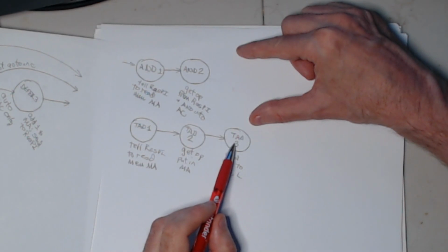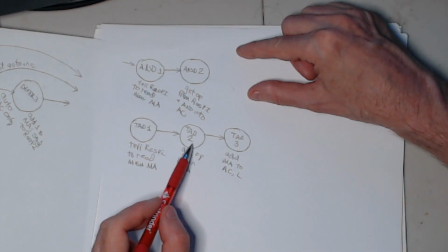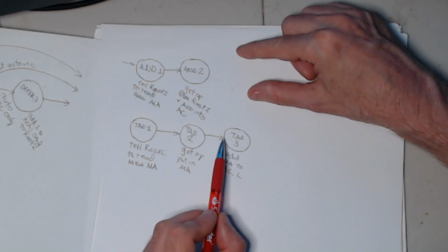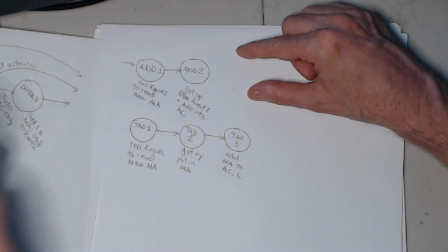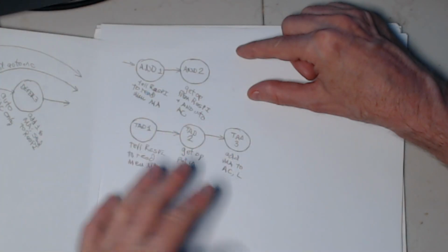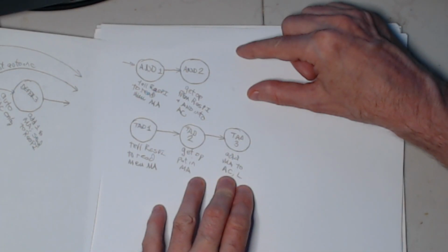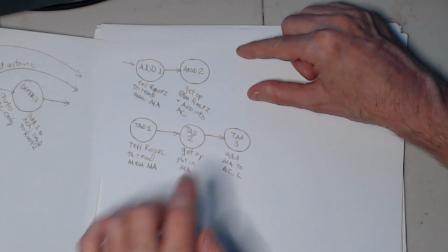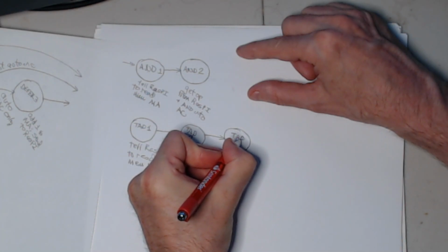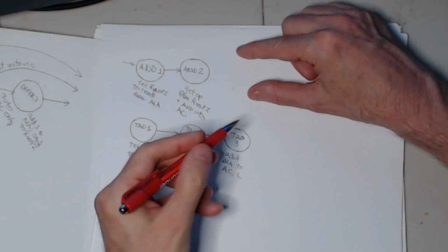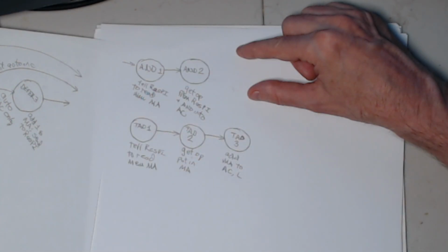So this gives it a whole cycle. It's already got the value from the Raspberry Pi in the memory address register, so when this thing kerchunks in those values, it doesn't have to wait for it to come from the Raspberry Pi. It's got it immediately, and it can start doing the addition right away here. So that lets it go a little faster, or gives it time to get all the way through the ALU addition circuit.